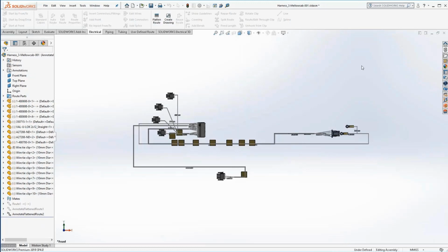At this point, you may change. If you don't like the shape that SOLIDWORKS is proposing for your harness, you may edit that. You can stretch some branches and make it larger, move them around, move the connectors. You can do whatever you need to do, okay?